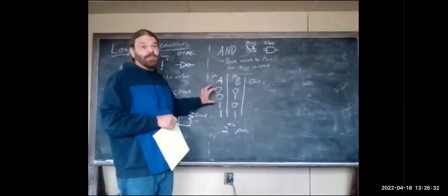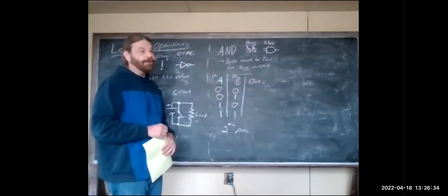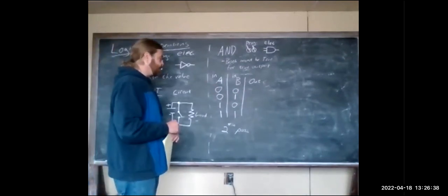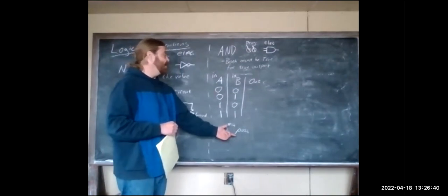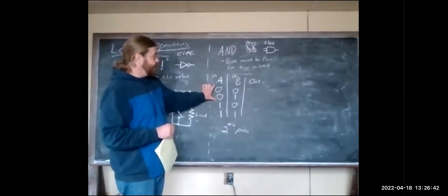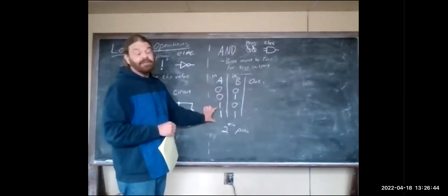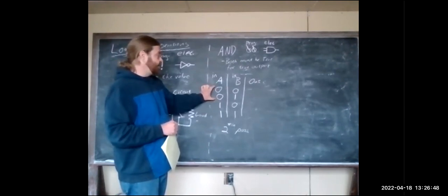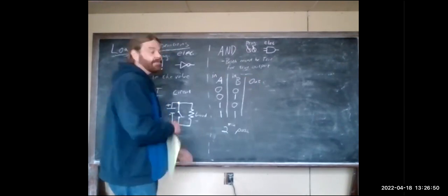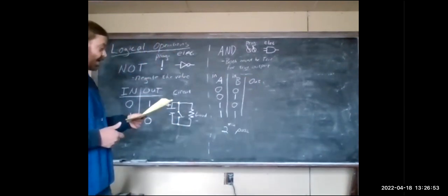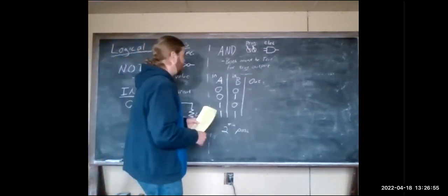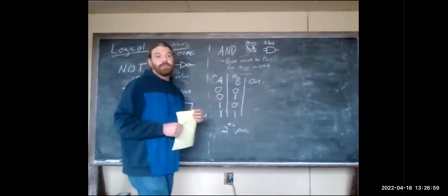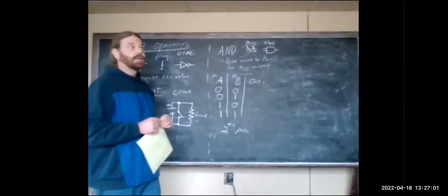Trivial in this case, but when we get to a situation where we actually need a truth table, patterns like that to make sure you don't miss anything are very useful. So the number of possibilities you have, cut that in half. Then half of them are zeros and half of them are ones in the first column. And however many of those you drew, cut that in half and keep cutting it in half for all your columns. So then our output, well, we only get true when both of our inputs are true. Right?